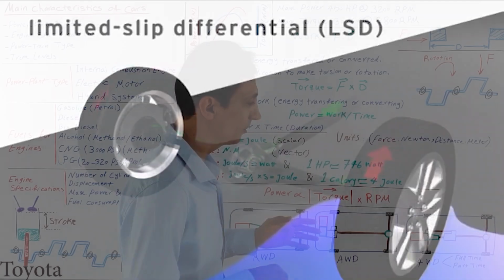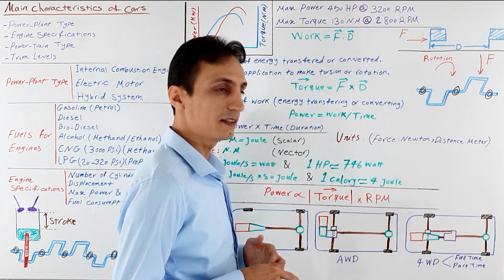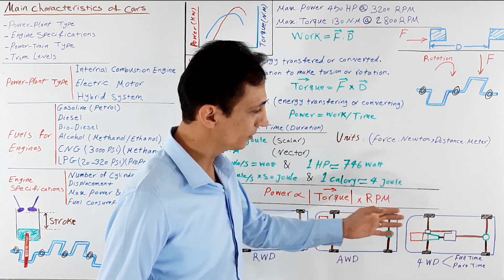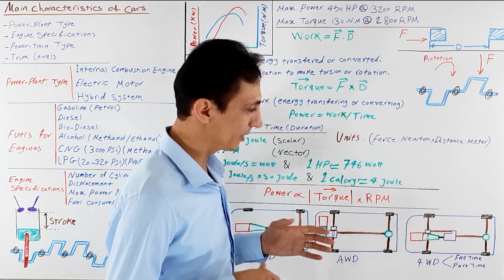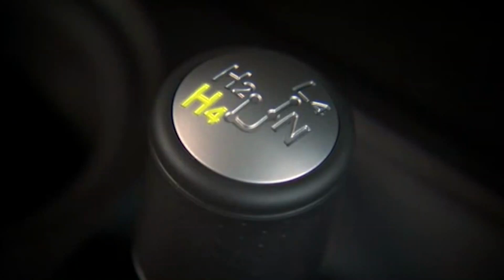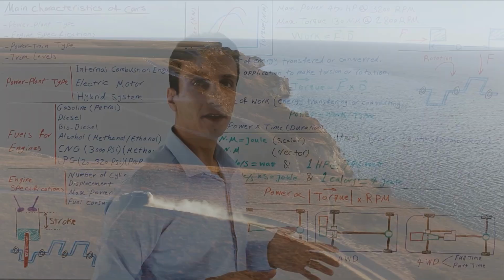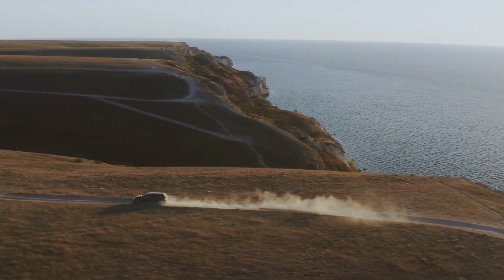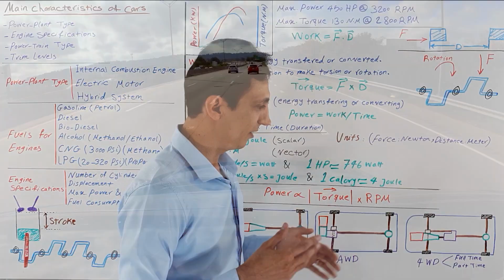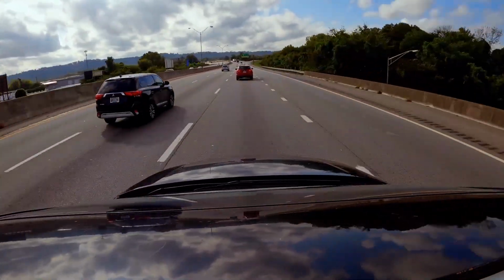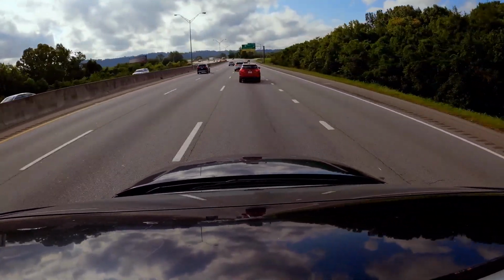But further development made the path for the emergence of differential locks and also transfer cases that make it possible for the driver to select high and low speed driving modes. These systems are not very efficient and are suitable for off-road driving, and if you use them on pavement and highway driving, maintenance costs rise and powertrains wear more.